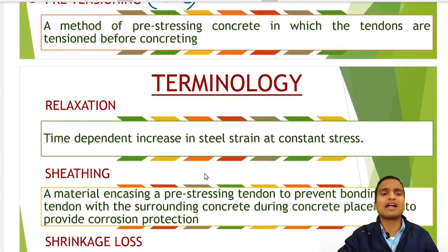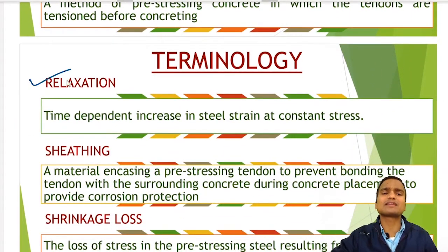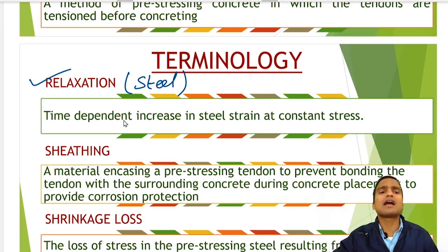Okay, and next term is relaxation. Relaxation, when we have discussed the creep, we have also discussed it. Relaxation is the property of steel bars and it's a time dependent strain for the sustained loading in the steel.